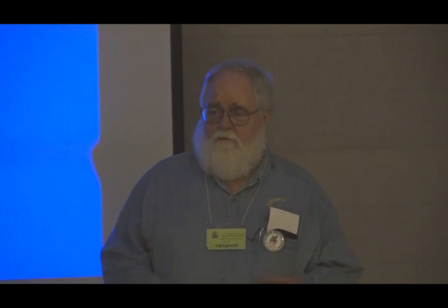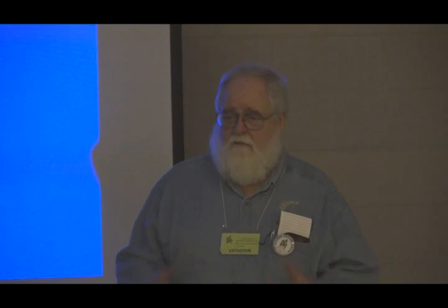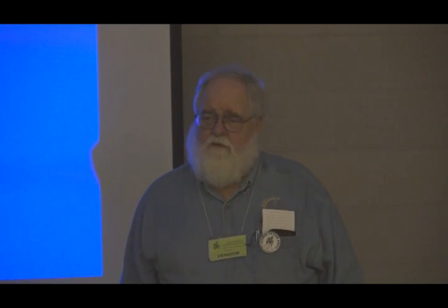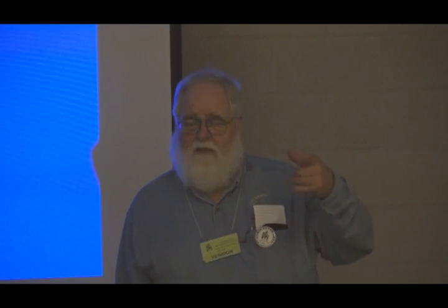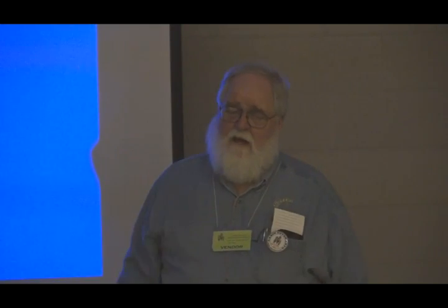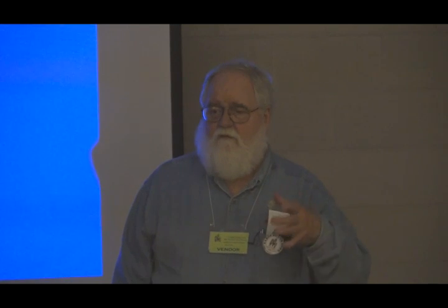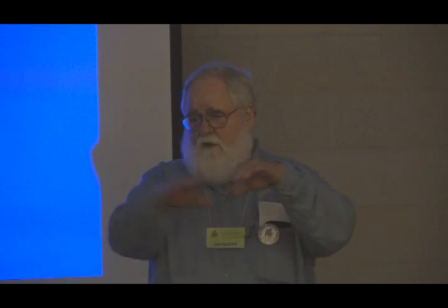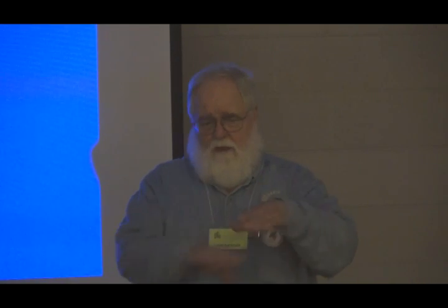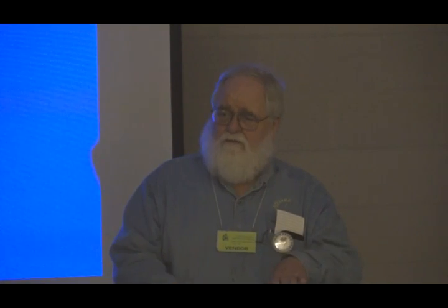What they would probably do is change the tool diameter or something like that, but they use the same steps, and then when the G-code gets generated, it would take account of the tool that they used. They would have to go down that screen, choose edit tool, and edit. I didn't show that here, but you could have multiple tools within a job. You might open with a fly cutter for surfacing, and then have a tool change to a 1/4-inch mill, and then do some pocketing or something.